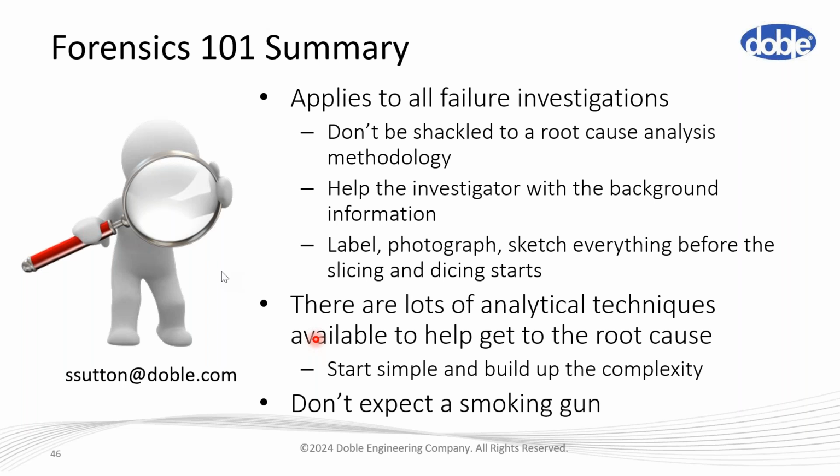In which case, sheath testing, so measuring the resistance between the metallic sheath and earth, and if the jacket of the cable, the oversheath, is damaged, you'll pick that up, and then you can start to find ways of narrowing down where it is to repair it.